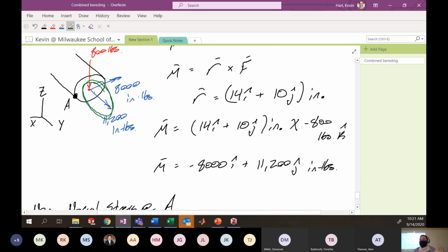This will become important when we talk about the shear stress that arises from torsion, because this arrow is along the axis of that member. So the only thing I have to concern myself with in this problem is this 8,000 inch-pounds, the bending load being put on this cross-section. Here this is a bending contribution, and this here is a torque.